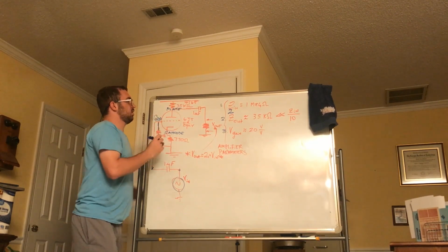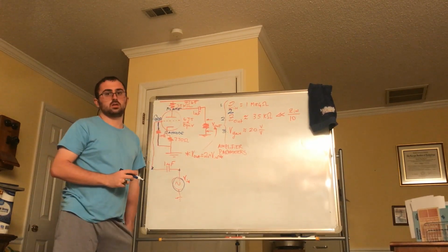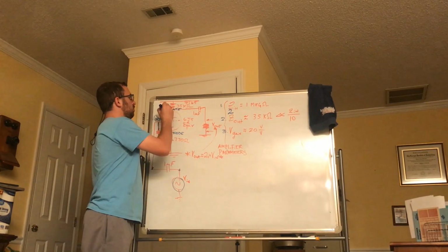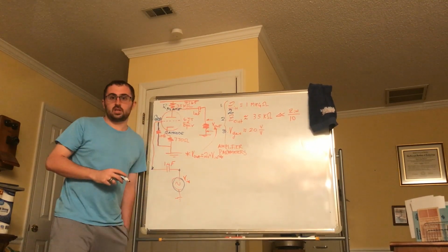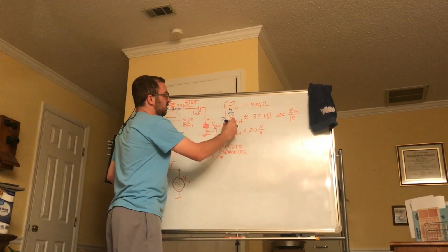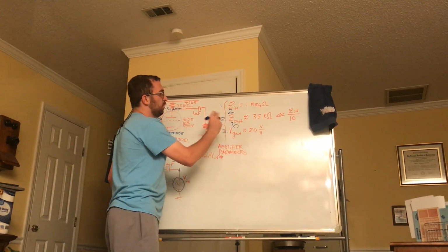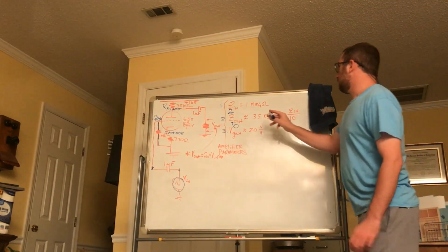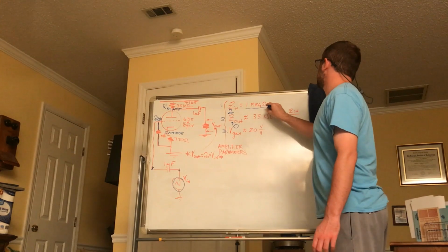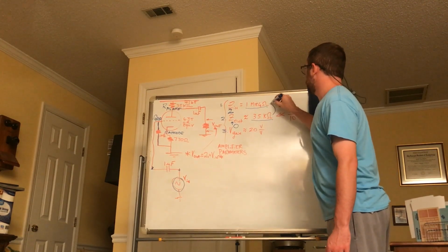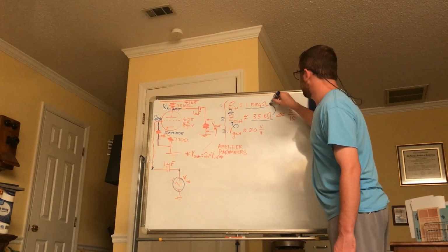So your output impedance, the largest impedance it faces, is R, which is what it was called in the last video. And here it is 35 kilo ohms. Ideally, this guy would be 0. But, worst case scenario, you have to keep your input impedance much larger than your output impedance. And as you can see, this guy is orders of magnitude higher, so we're good.